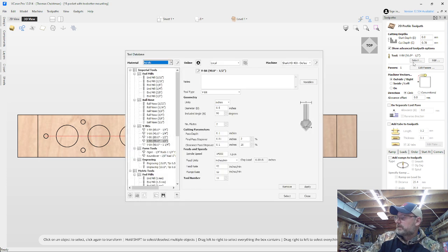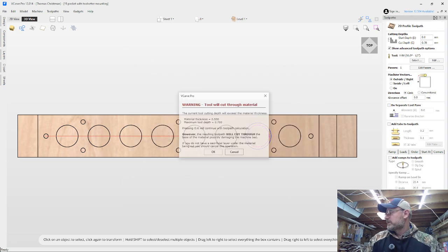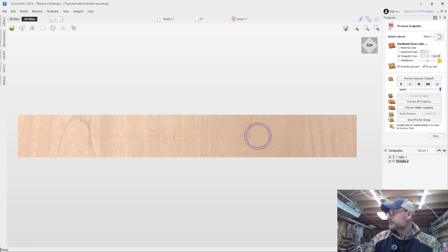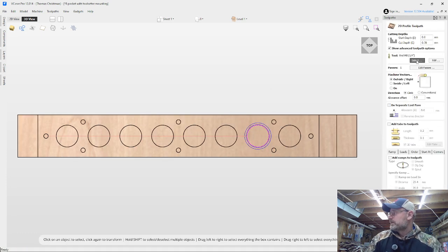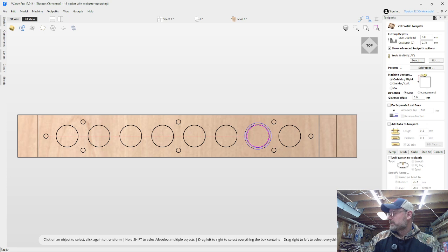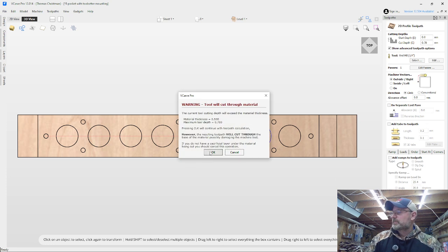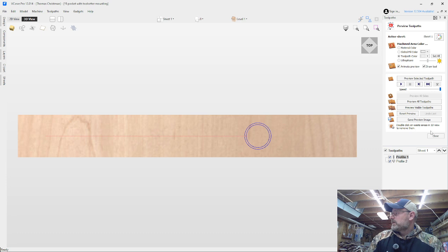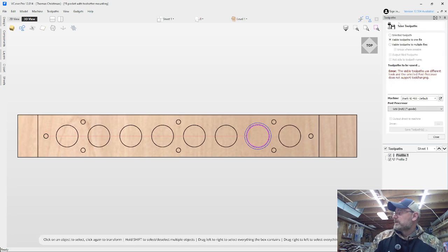And that's tool number, let's just say that's tool number 2. And calculate. Okay. Let's go into this one and let's see what this one says. So it's tool 4. Let's just call this tool 1. Select. Okay, and calculate that. Okay. And now if I go to save, now see, because I have 2 profiles with 2 different tools, now it's going to give me this error because I'm on this Gerbil inch G code. It gives me an error.